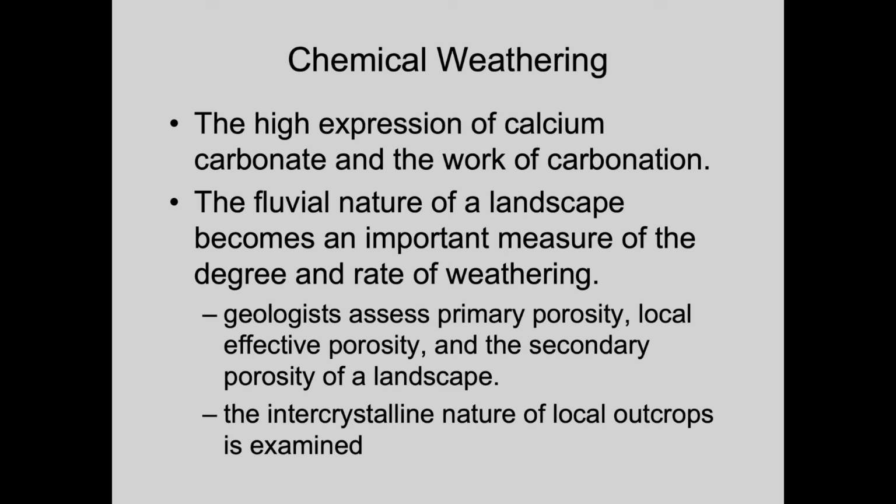A secondary measure, or a second thing that geologists will address, can be further labeled as effective porosity of a bedrock type. This is the estimate of the degree of connection between voids that make up the overall primary porosity of the rock itself.